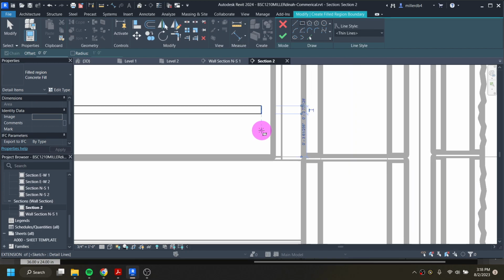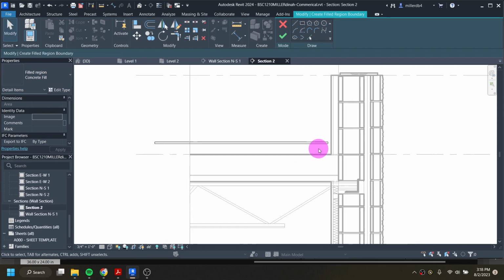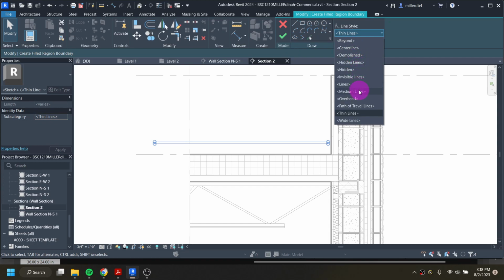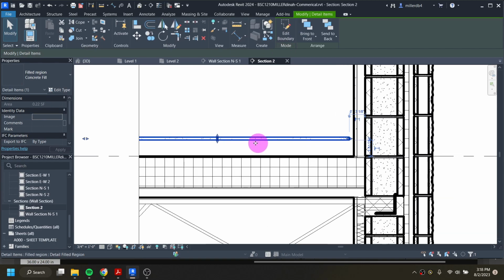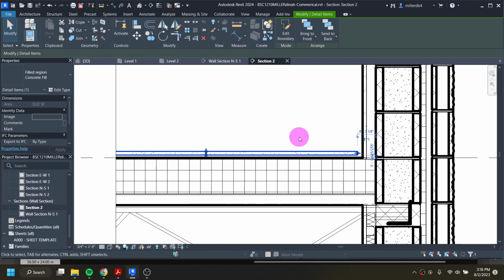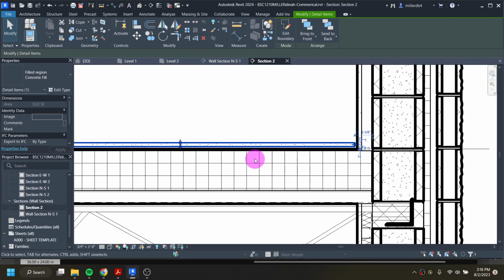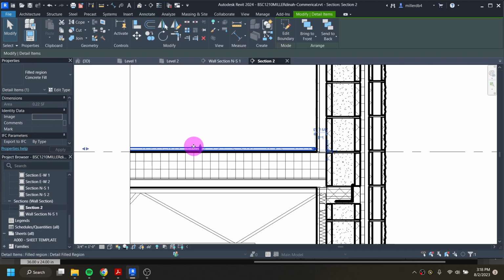And then I also want to adjust its line weight. So I'm going to hit escape a few times to get out of the drawing tool. Then I'm going to highlight the entire piece and change its line type from thin lines to medium and click OK. And what I've done is I've made that box. I can move it into place if I want. Keep in mind where we're moving it is just going to be kind of eyeballing it a little bit. Sorry if that bugs you. But I don't have the right fill within it, so I can change it afterwards.